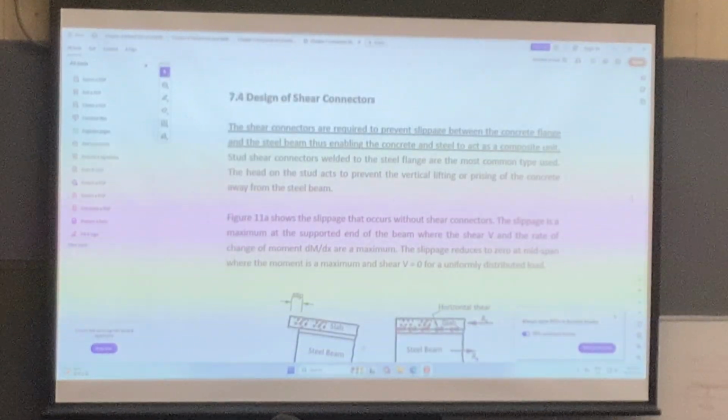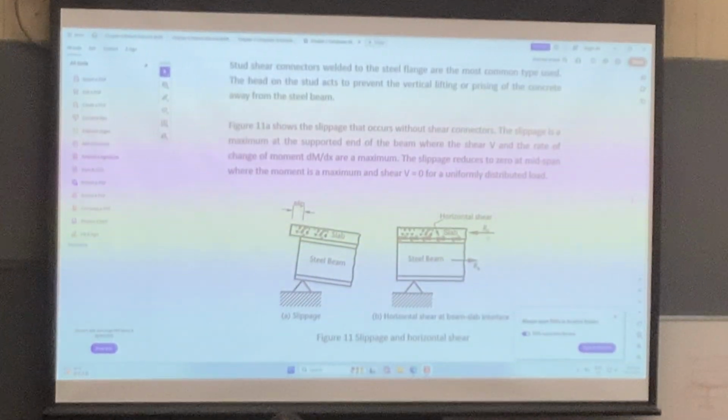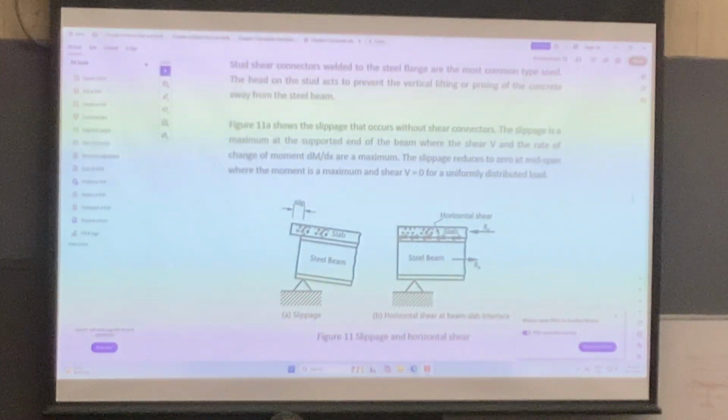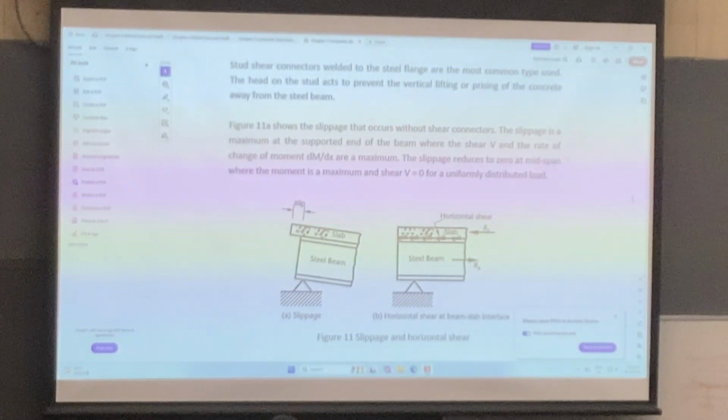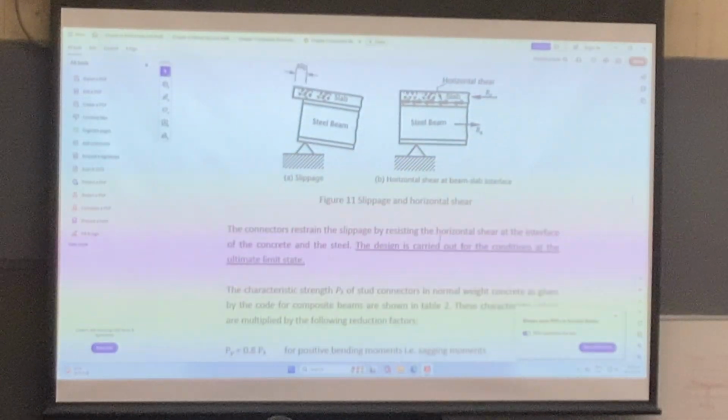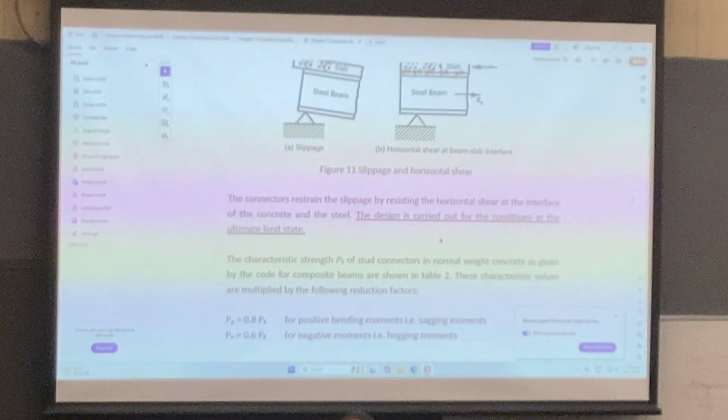Okay. So here, if I compress it, the slab can take compression, and if I tension it, the steel can take the tension. So I have to provide enough shear studs to lock the section so that they cannot slide against each other. At this condition, the design has to consider how many shear studs are to be provided.